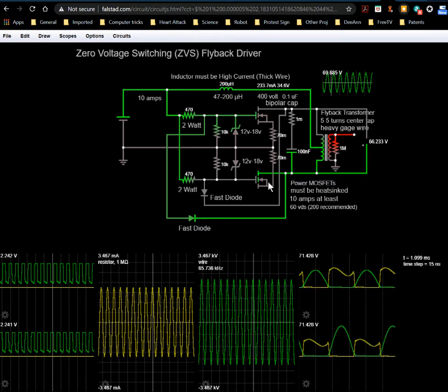Now, there isn't really a shoot-through current here, because this isn't like a CMOS totem pole or an H-bridge, so you don't have shoot-through, because this is ground here. This isn't like a load's connected, this is ground. These two can't short circuit through each other because there's ground in the way.